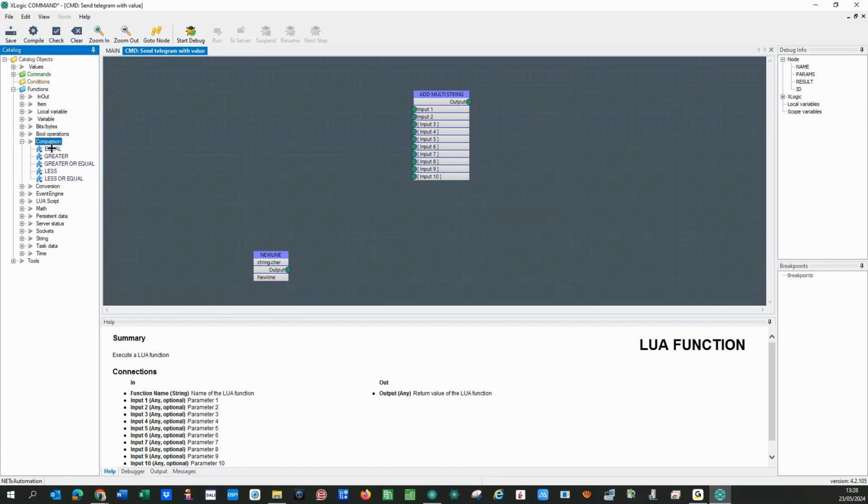Now, we create a condition, and the conditions were these: equals, greater than, using these comparisons, but also Boolean operations. This is really fantastic because you can do logics: not, and, multi. If it's Boolean, if it's a number, you can get true or false if this is on, if it's a string. Boolean operation, also interesting, and also really powerful, the bit and byte operations, because you can get information, for example, from a word if one bit specifically is set or not.